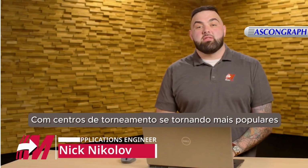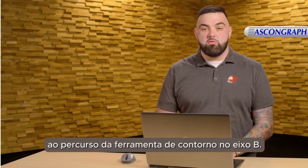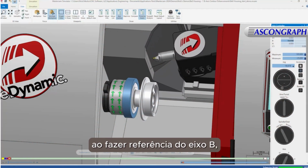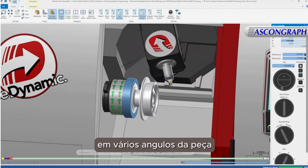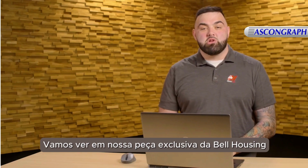With multitask turning centers becoming more popular, Mastercam 2024 has made some significant improvements to the B-axis contour toolpath. If you're new to the turning side of things, when referencing the B-axis, we're talking about the rotation of the mill turn's milling head that enables it to perform work on various angles of the part, both on the main or subspindle. Let's take a look at our bell housing signature part and dive into it.